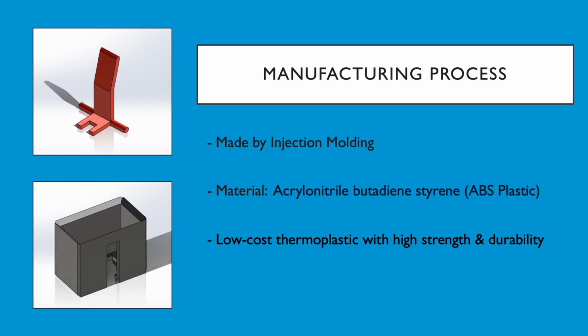The reason we are using injection molding is because the new components for the design are simple parts that don't require any special material. Injection molding is a better method than something like casting or forging because it is more suited for the parts needed. Injection molding is a very fast process and can produce large quantities with minimal error. Injection molding also produces very little waste material compared to casting methods. Although it can be expensive to create the mold for injection molding, it is still ideal for mass production and the best option for these 2 components.